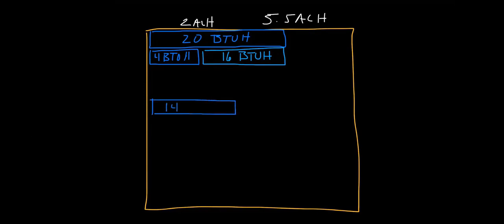The all-air system would be delivering 14.5 BTU per square foot. This is the maximum turndown for the system. While the chill beam is still supplying 4 BTU per square foot with the primary air, the balance of the cooling is provided from the coil in the unit.